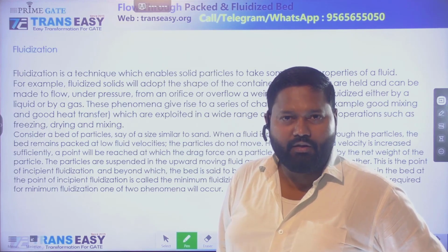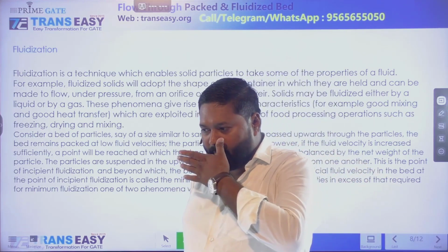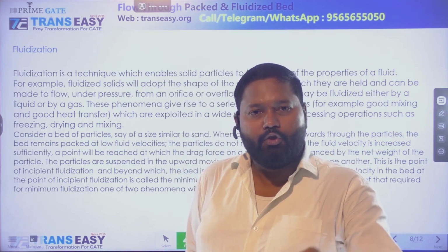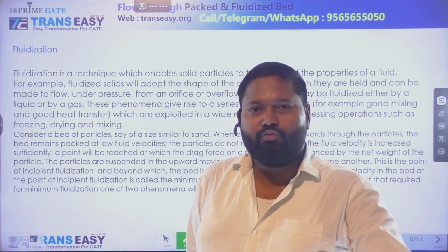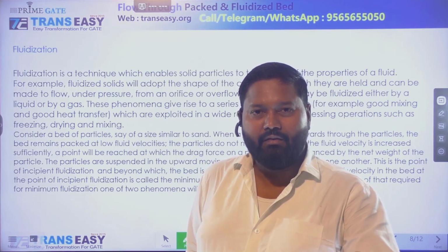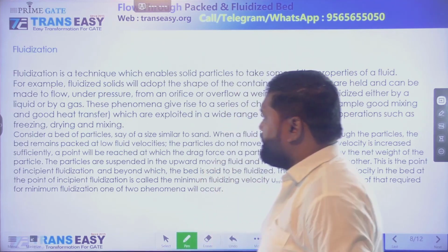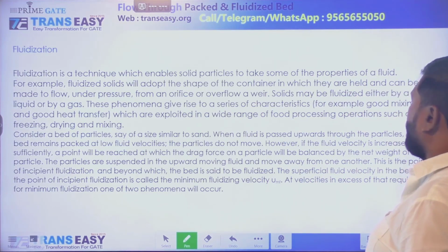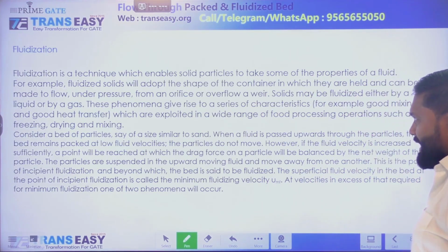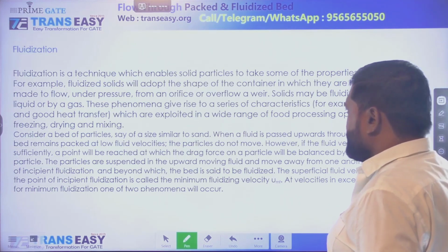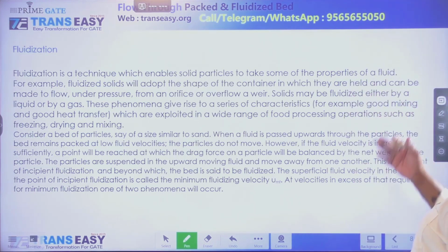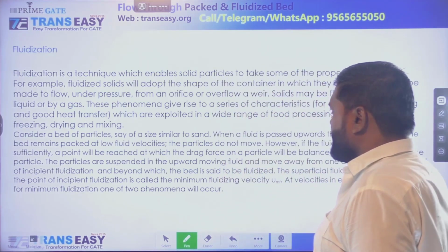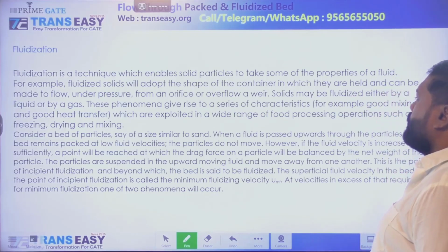So these are not fluid, but if the bed is fluidized, some fluid properties are actually shown by the solid particles kept in the bed under fluidized condition. For example, fluidized solids will adopt the shape of the container in which they are held and can be made to flow under pressure from an orifice or overflow a weir.